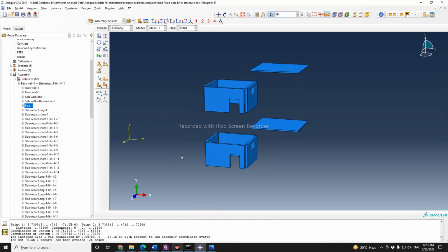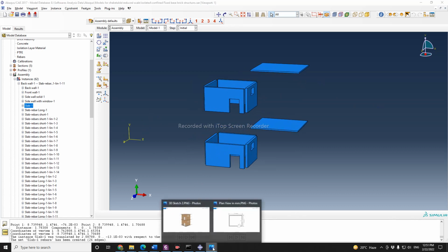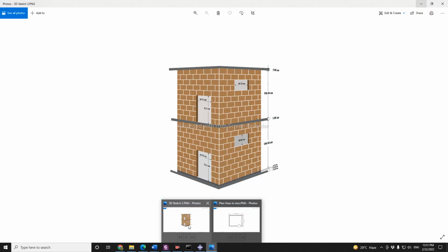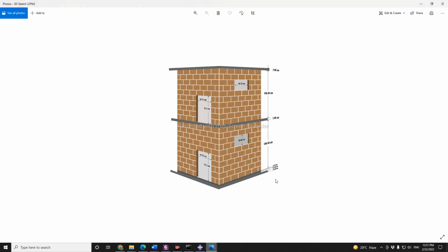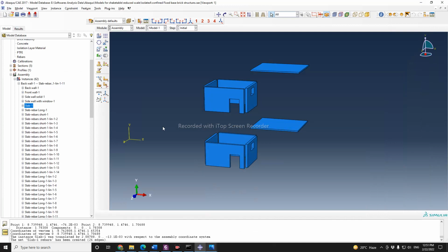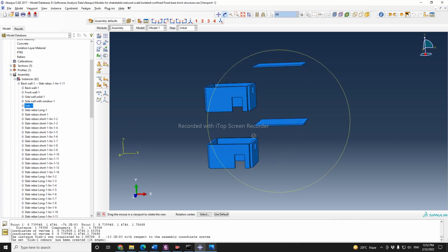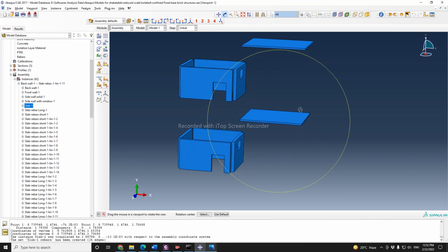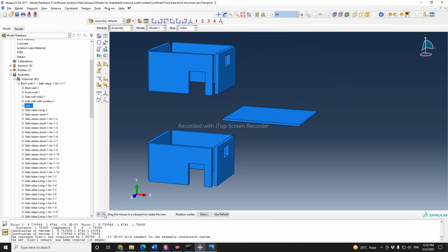And there is also a base pad. Actually I am trying to model this thing, and there is a base pad at the base, so I am also interested in modeling that base pad as well. I think I can use the slab as my base pad. I only need to increase the thickness of this slab, and also I will vary the dimension of my rebars.